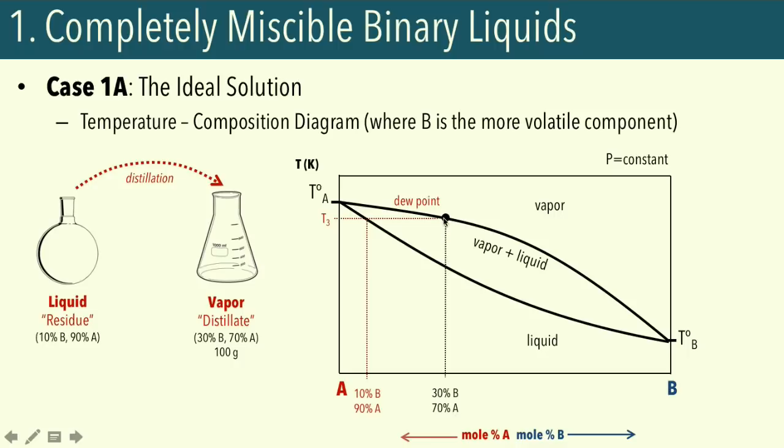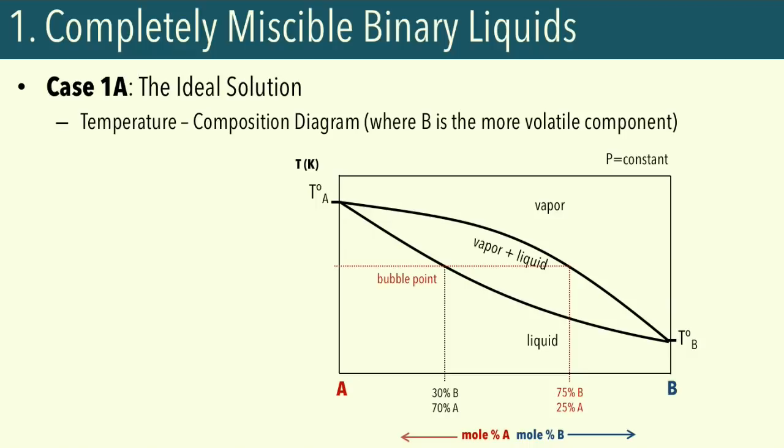So the range of distillation temperatures that are most practical are between the bubble point and the dew point. But we typically use the composition of the vapor at the bubble point as a basis to determine the maximum possible separation that we could do for a distillation process.